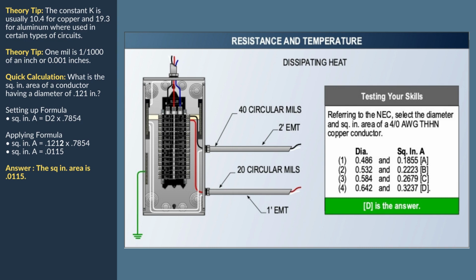Consider two conductors having the same resistance, and generating the same amount of heat. Notice, they carry the same amount of current. If one conductor has a greater surface area, it can carry more current without damage, because it can dissipate the heat faster than the other.